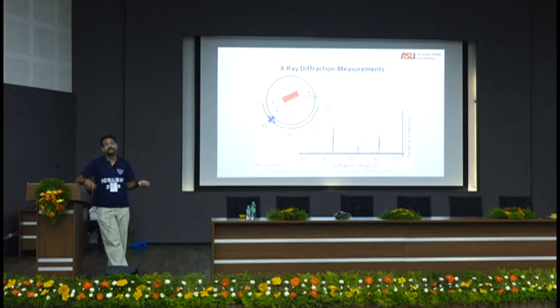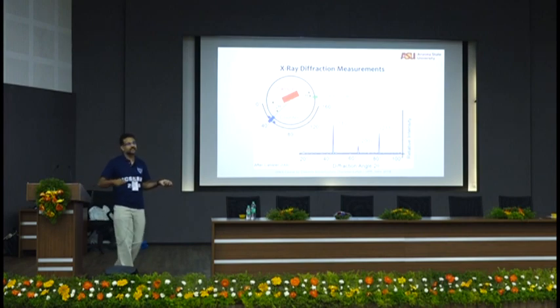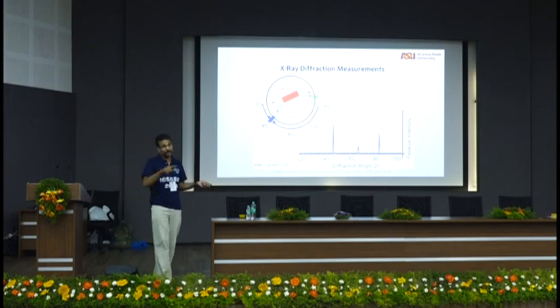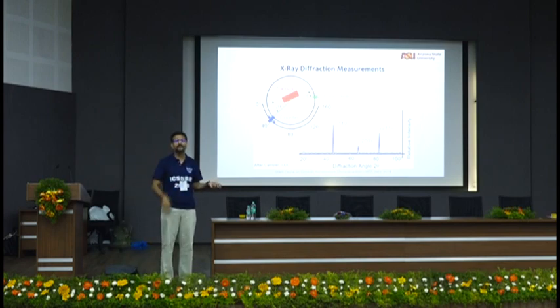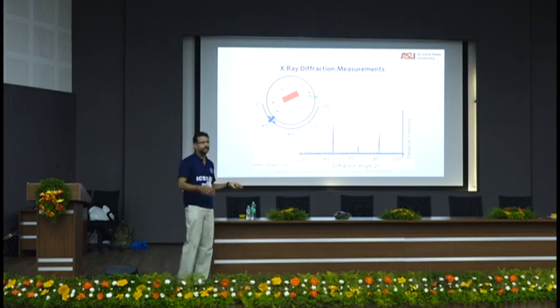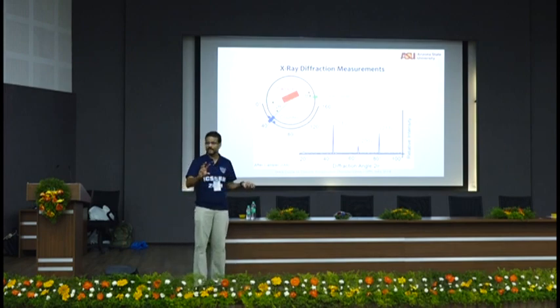Sometimes 0 to 90 takes a day to do this X-ray. Others also have to use it, so they may not give you the X-ray machine for a complete day. So you have to do it faster. If you do it faster, your X-ray will be noisy, but you can still find out what the peaks are and the software will help you clean it up. So it depends on the rate at which you rotate.